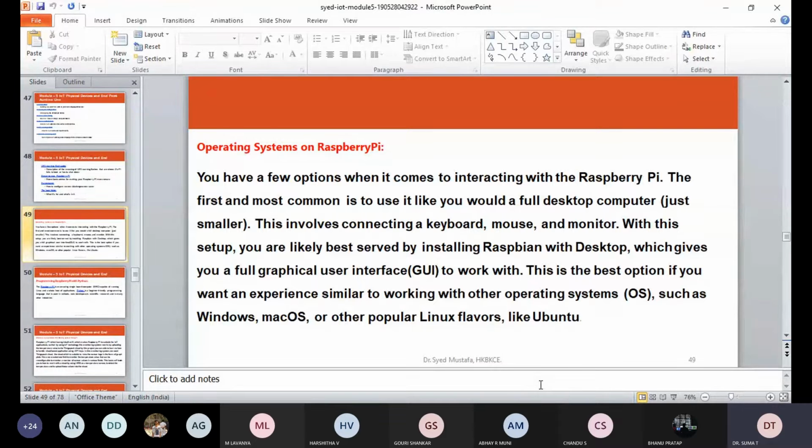We recommend using Raspbian: tick the box next to Raspbian and click on install. Raspbian will then run through its installation process. Note that this can take some time. When the installation process has completed, the Raspberry Pi configuration menu, raspi-config, will load.